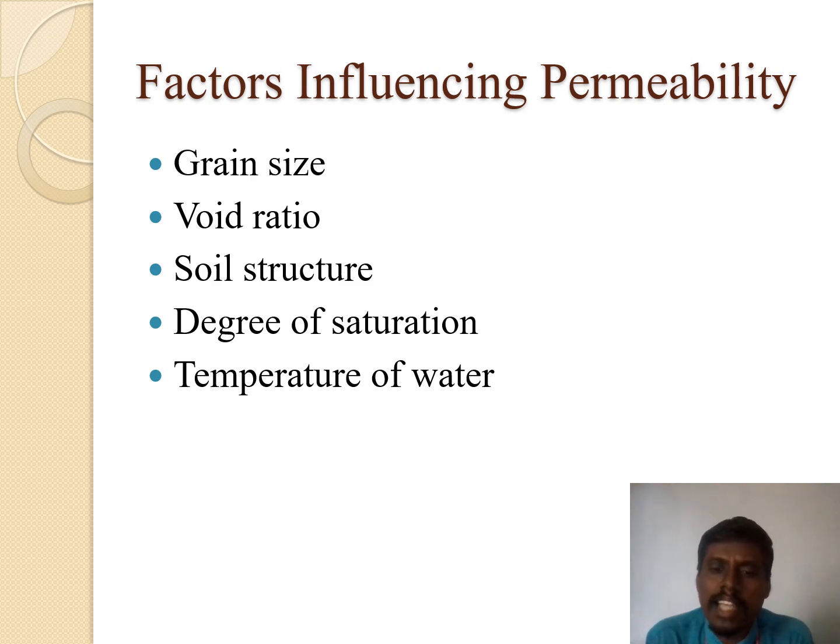And the next one is the soil structure. Based on the soil structure, the permeability also differs. For some types of clay particles the permeability will be very low. So in those particular cases, the permeability coefficient will be very small.